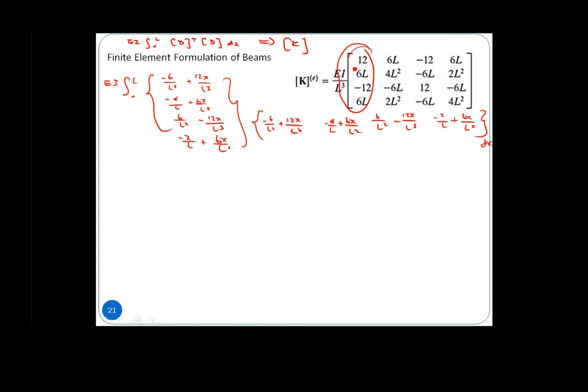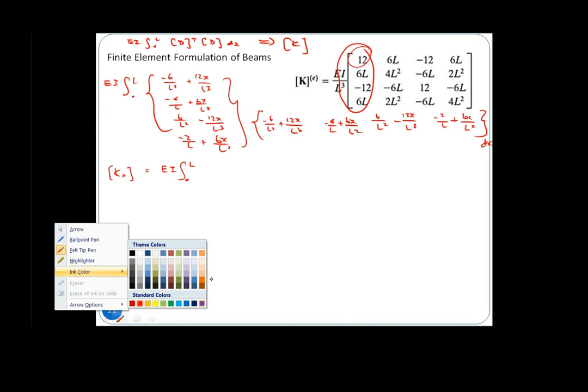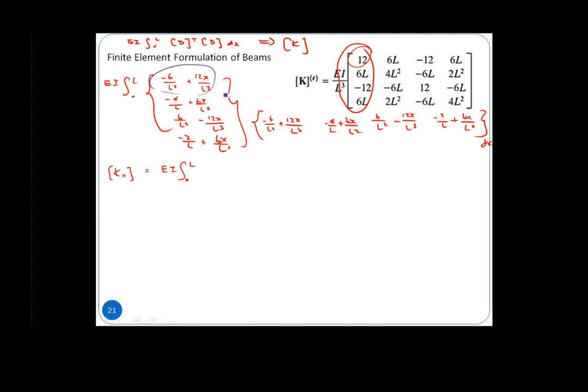So if I want to get this K11, so our K11, which is here, is of course equal to EI, integral from 0 to L. Maybe I use different colors. It will be this, multiplied with this. So we have 4 times 1 multiplied with 1 times 4, so we will end up with a 4 by 4 matrix.